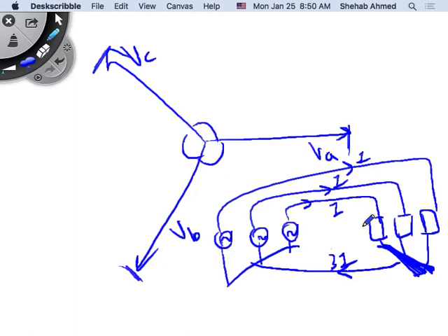Since they don't care, we said, okay, let's phase shift them by 120 degrees. Then the sum of the currents here will also be phase shifted by 120 degrees, because this is 0, 120, 240. And when you add 3 phasors that are 120 degrees apart and equal in magnitude, the sum will be 0. So we said that the neutral current will typically be 0, and in transmission systems we typically remove the neutral cable. In distribution systems we will leave it.